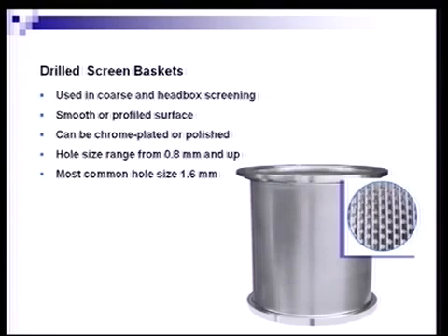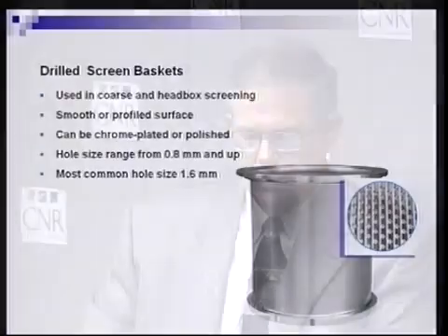We have corrugations on the surface in order to provide micro turbulence, which gives us better consistency and better flow characteristics. Remember, we get more flow with a turbulent flow than we do with laminar flow, so we want to stir that surface up. Using corrugations in the screen plate design is one way to do it.